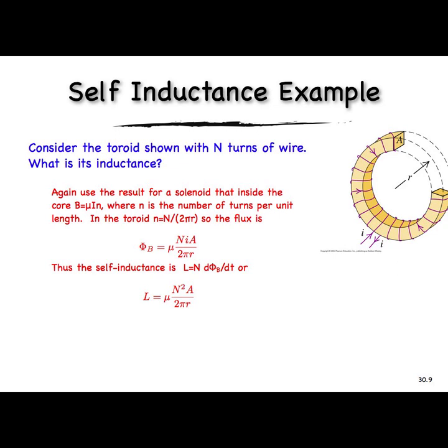And so we can express the relationship between the induced EMF and the change in current in exactly the same way we had before. Before we said that EMF was minus M dI/dt. And now we'll just replace that minus M, that constant of proportionality that talked about the coupling, the magnetic coupling between two circuits, with this constant L, which is called the self-inductance.